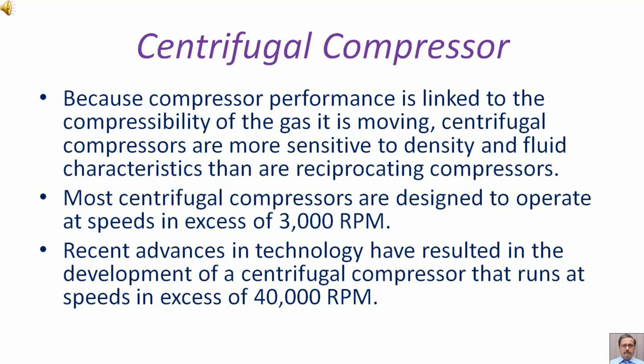Because compressor performance is linked to the compressibility of the gas it is moving, centrifugal compressors are more sensitive to density and fluid characteristics than are reciprocating compressors.